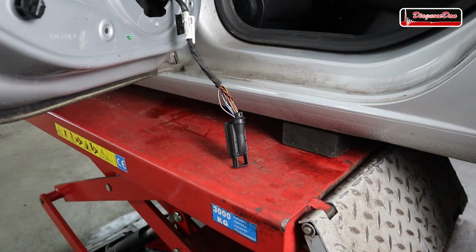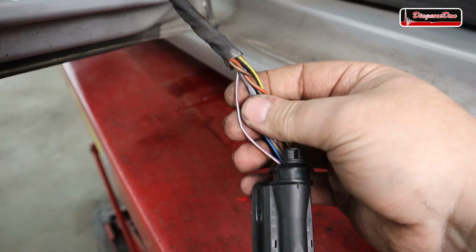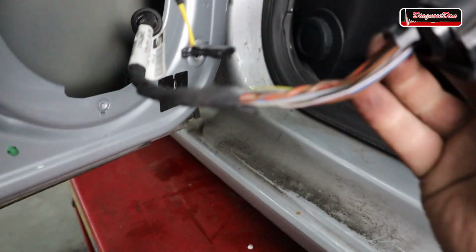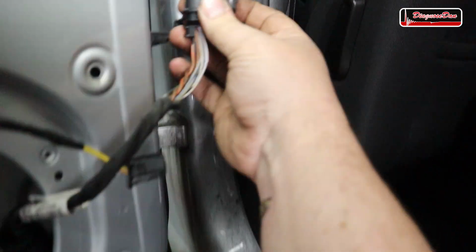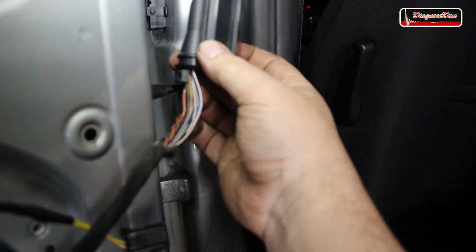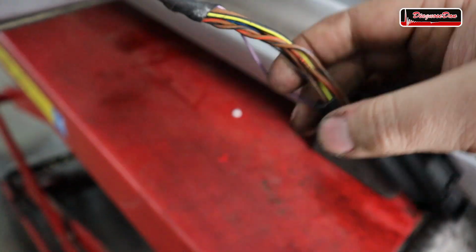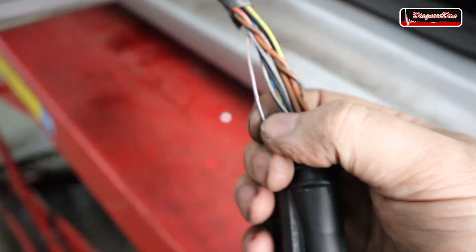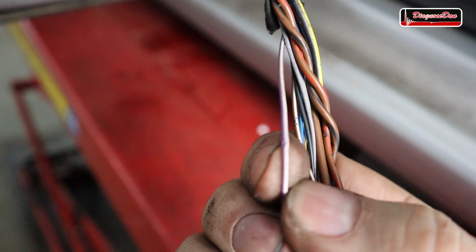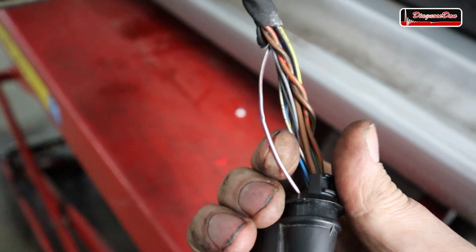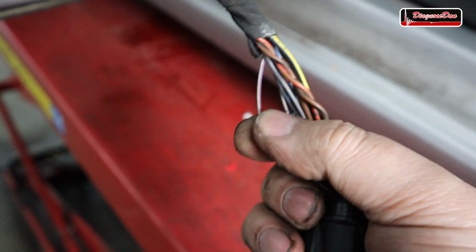broken wire. Now before I start peeling back that tape, I moved up that grommet a little bit higher up that wiring loom, and now we got a clear view of the wires that are normally in the hinge area. Now this is where you would expect those wires to break because this is where the wire flexes all the time. Now this is a little purple and white wire. Now this wire is broken and you would expect it to be broken right here.